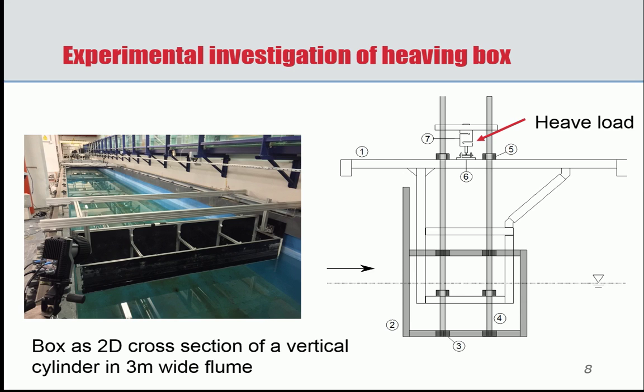So we built a large model, it's about 3 meters wide, and one of the advantages of doing it in a 2D tank is that you can do very long random sea simulations. We then built a rig that you see here. In this particular configuration, it's restrained so it can only move in heave, and there's a load cell right at the top there, so we're measuring the heave load. In another setup we would take the load cell out, let it freely heave and measure the heave displacement.